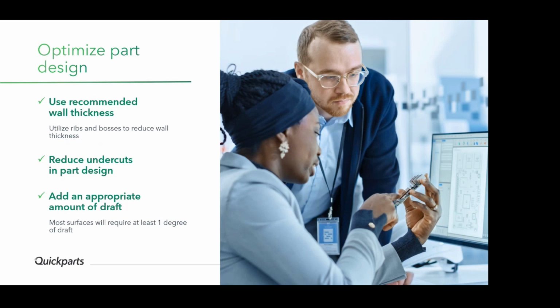Try to reduce undercuts, right? If you have some features that cause undercuts, you may eliminate undercuts maybe by adding some shutoffs if possible, or if you have to have undercuts, then try to reduce the number of directions.